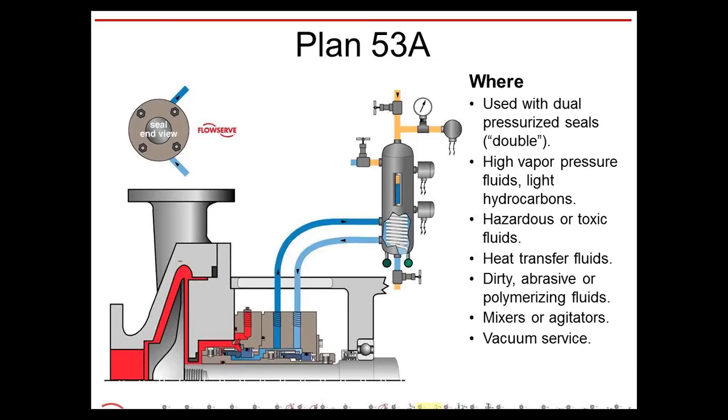Because this is pressurized, you do always want to have some sort of pressurization device acting on the seal chamber. Generally, it's nitrogen at a certain pressure that comes in, and you can see on the top of the seal pot a yellow line with a black arrow right directly on the top. That's where the pressure is applied. Usually you set that pressure to 25 pounds above whatever the process box pressure is, and let it go.